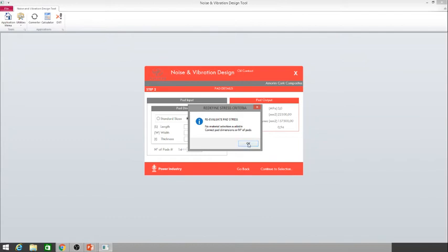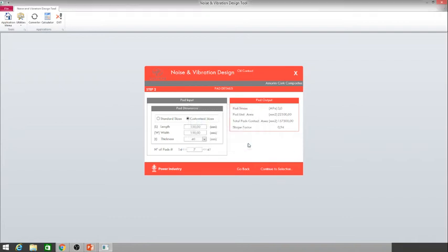So the software doesn't allow us to go further if the parameters are not within the acceptable limits. 7 doesn't work. The software already warned us that it should be between 14 and 41. And we want again a stable solution. So any number of pads between 14 and 41 will work. The software will continue and will provide the output, but we need to have a stable solution.